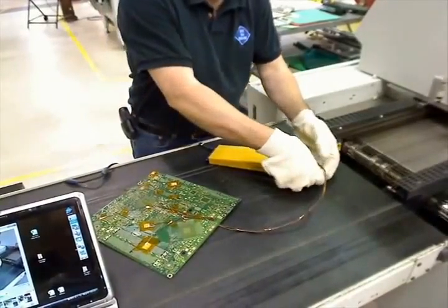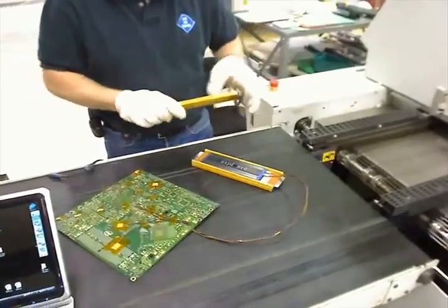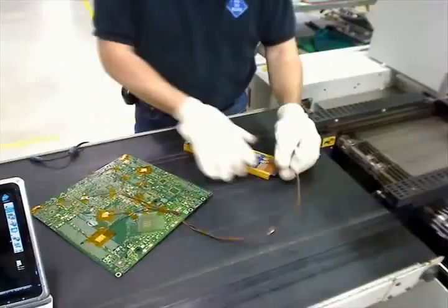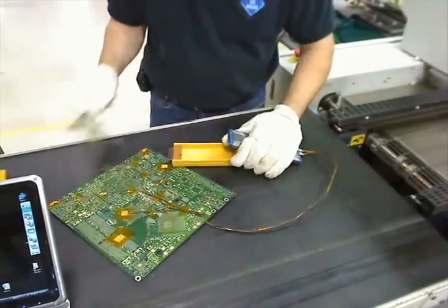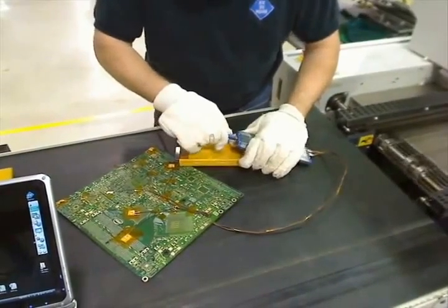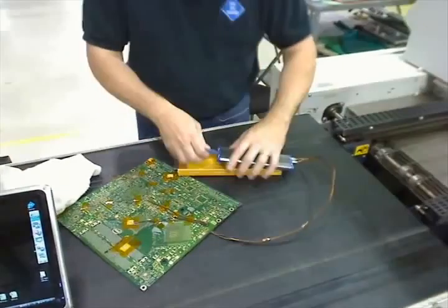Or you can wait for the unit to exit and connect a data log cable to your unit. Some units, such as the one pictured here, have special shielding that allows you to handle the unit fairly quickly even when exiting a lead-free process. Now that the unit has fully exited the oven, it will end logging data and begin analyzing your profile.